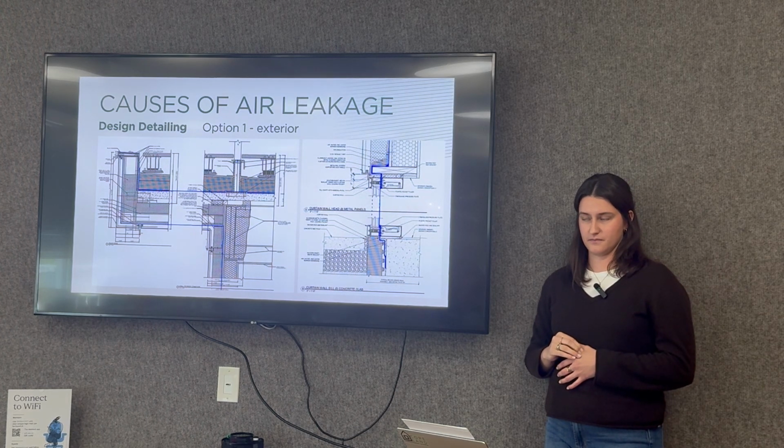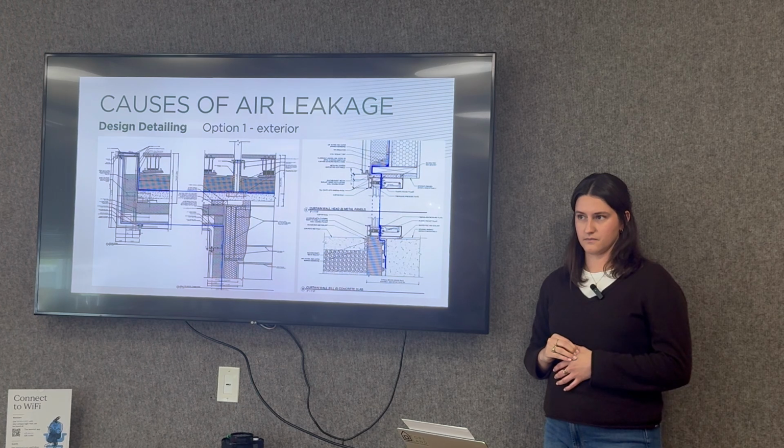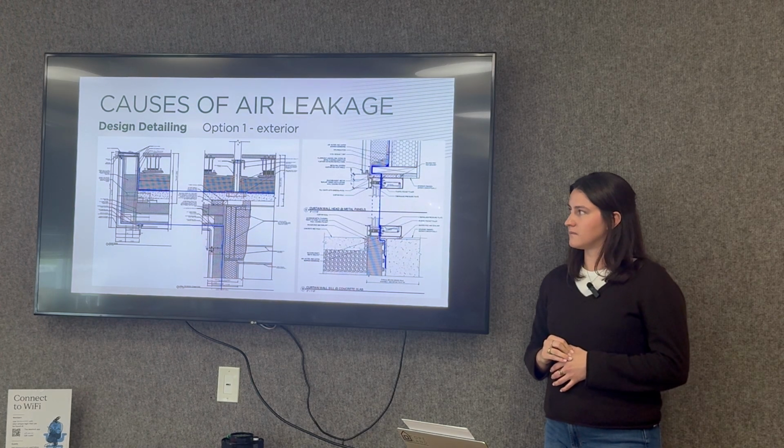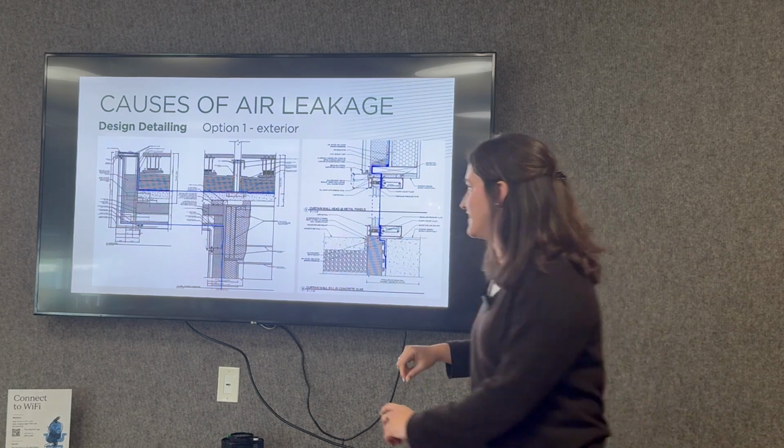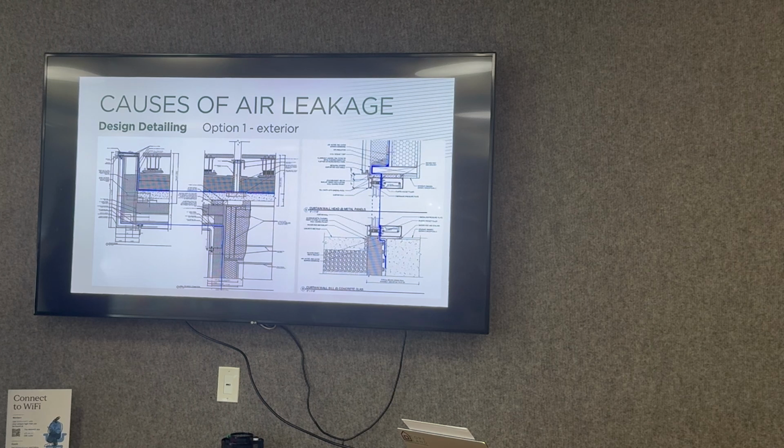The roof to wall transition, maybe a different contractor looking at it, maybe tie in the fire wall. Yep. Well, sure, there's that. I'm trying to understand this detail here. It looks like you're going outboard of the insulation on the soffit and the parapet, but you're inboard of the insulation up here. On the vertical wall, the parapet, you're outboard of the insulation on the metal panel. But when you transition from soffit to the wall, you go through the insulation back to what I would call the dense glass. And that's a detail of the sealant. They didn't provide it, but yeah, it is.